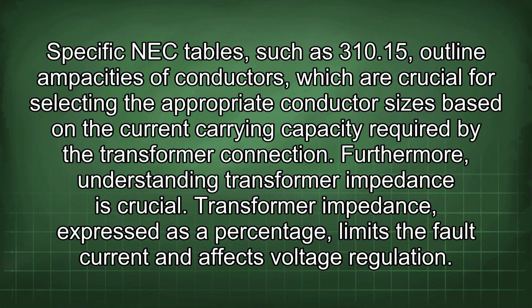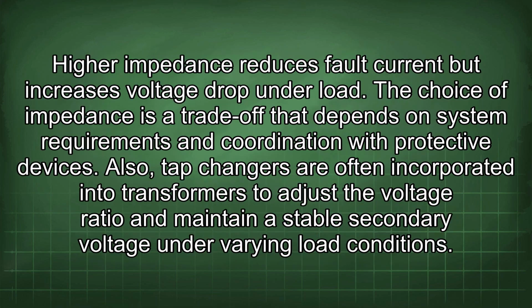Furthermore, understanding transformer impedance is crucial. Transformer impedance, expressed as a percentage, limits the fault current and affects voltage regulation. Higher impedance reduces fault current but increases voltage drop under load. The choice of impedance is a trade-off that depends on system requirements and coordination with protective devices.